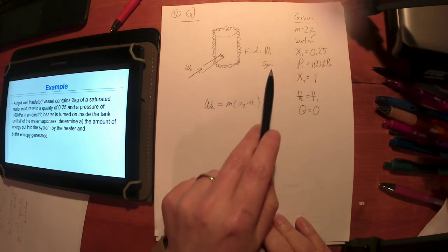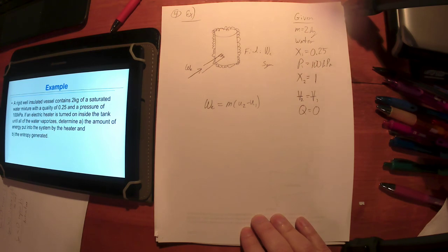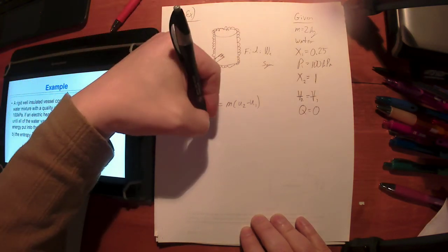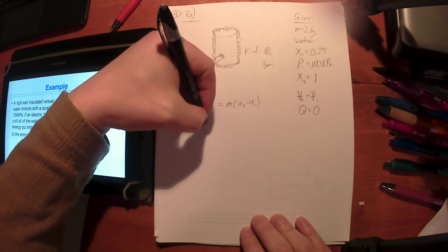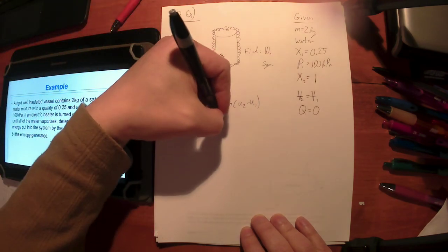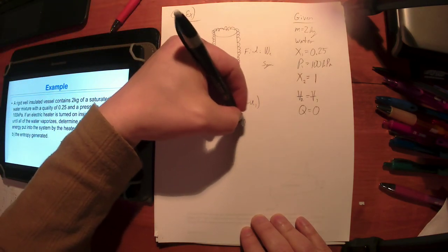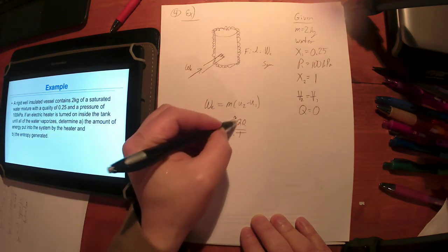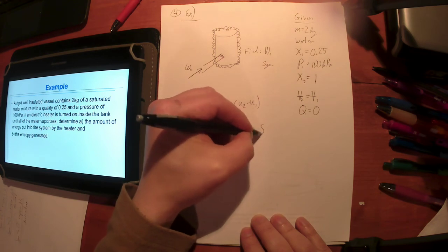So how are we going to figure out the entropy generated? Pause if you need a second. Right, so how are we going to find the entropy generated? Well, we just talked about this cool, brand new fancy tool. We said the entropy change, because this is a process going from state 1 to state 2, according to the second law, is the amount of heat transfer divided by temperature added up from state 1 to 2, plus the amount of entropy generated.